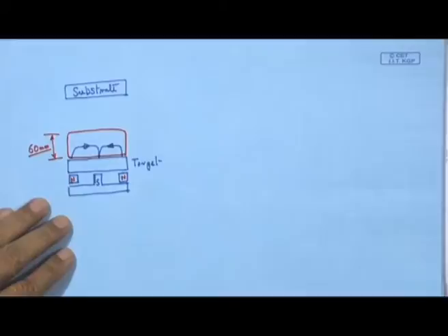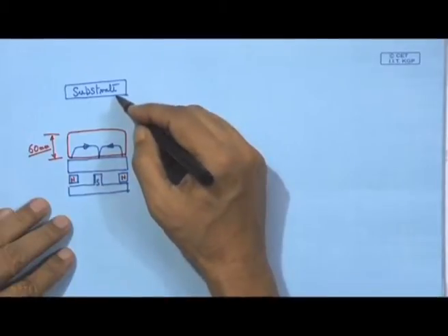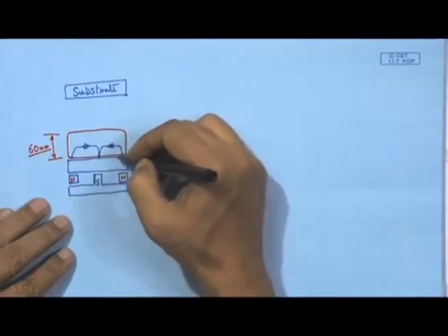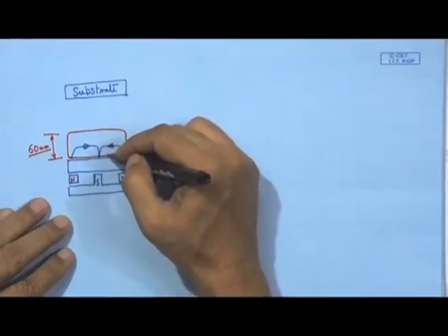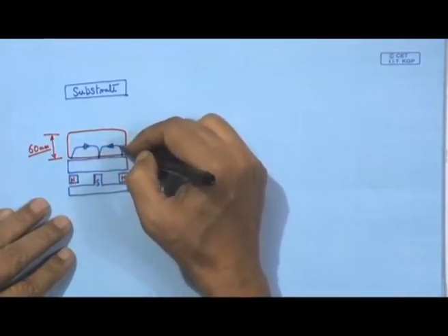If a substrate is placed within this plasma volume, it is subjected to ion impingement, and the whole region is full of secondary electrons confined within this volume.